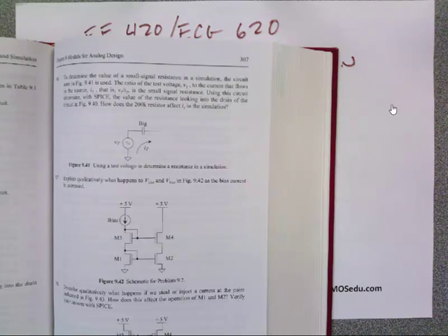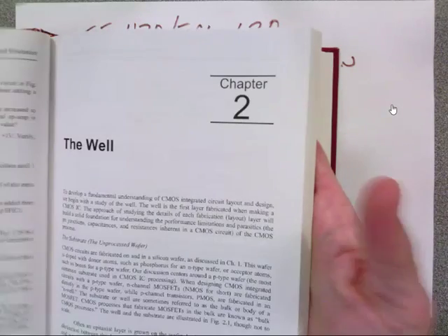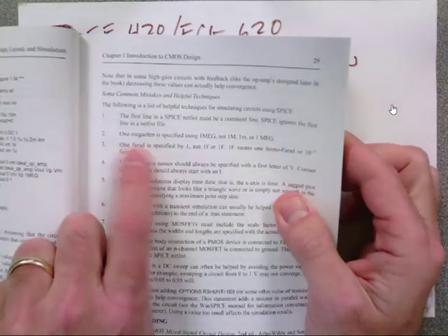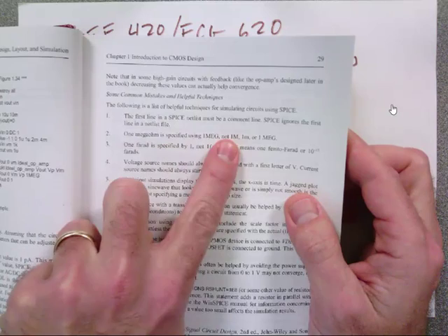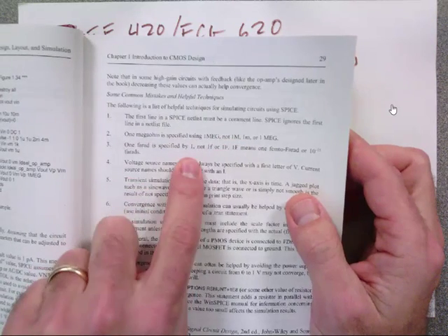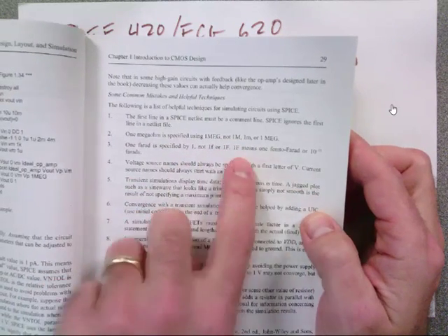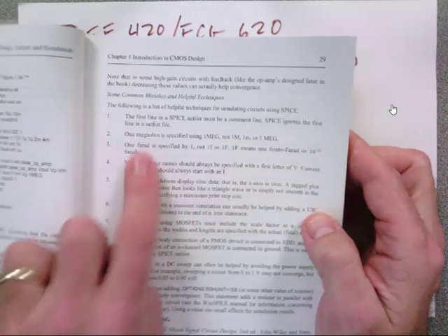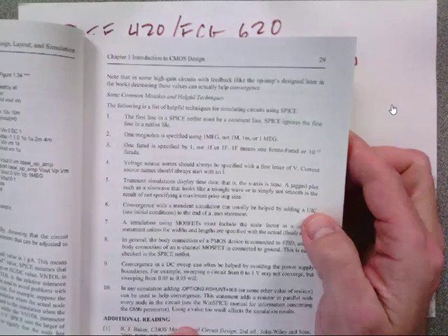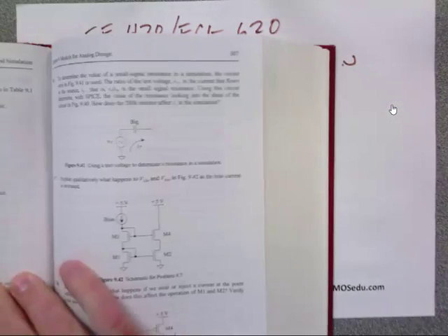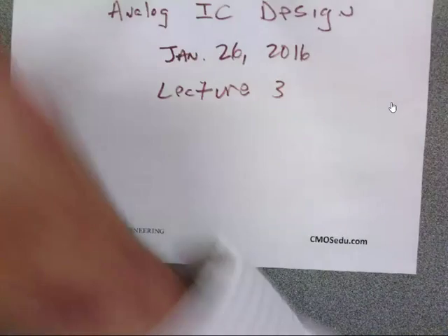So don't put the F. Everybody follow that? If you ask how would I know that, you go to the end of chapter 1 where the SPICE problems start, and you see that 1 megohm is 1 MEG, not 1 M, which is 1 milliohm. And 1 farad is 1, not 1F, since 1 femto means 10 to the minus 15 farads, etc. I go through this list, enabling you to be successful.